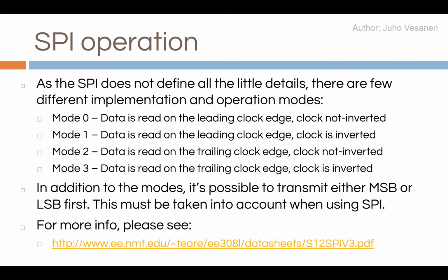Practically, mode 0 and 3 are the same, and 1 and 2 are the same. But anyways, most commonly these are leading clock edge non-inverted devices that we are using. But that's something you need to check from the datasheet.